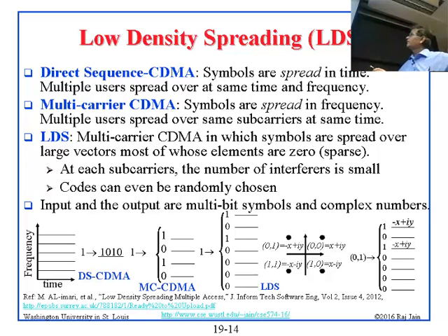We already know direct sequence CDMA, DS-CDMA, from the old days of 802.11 a, b, and g, right? It's spread spectrum. What we do in that one is we take the data bit and translate it into chips, and those chips go on the same frequency, but the chips are in time.